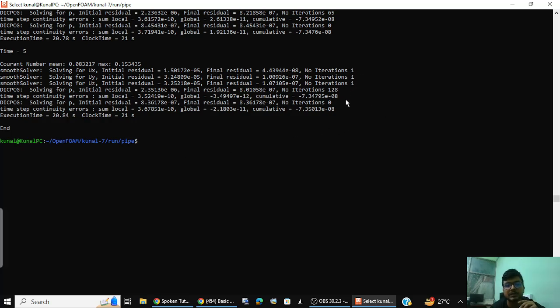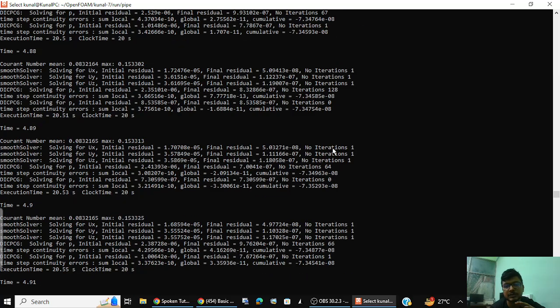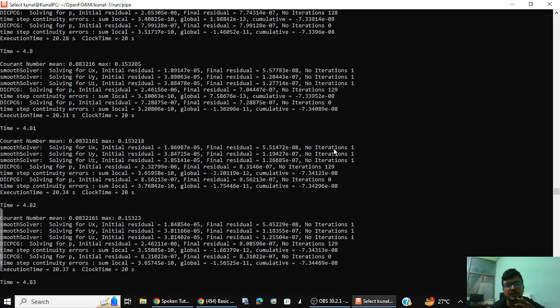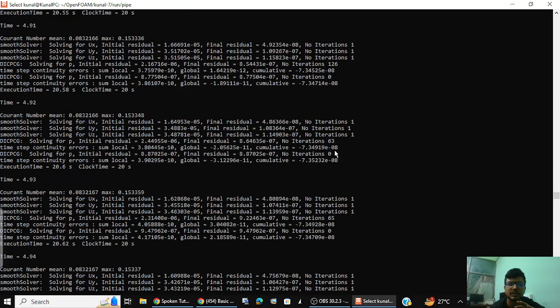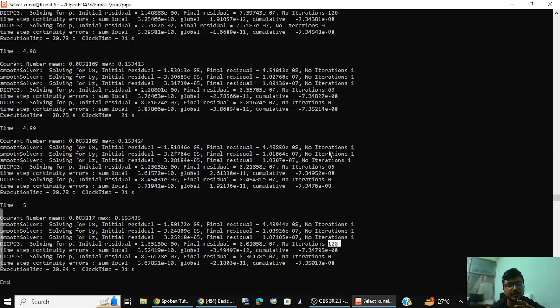And we are having one more iteration for the others with the residual under control. So yeah, it looks somehow good to me. The tolerance that we have put in here is 1000. So here it seems that the pressure is finding it difficult to converge, but yeah, for the sake of this tutorial, we are okay, and we can go ahead.